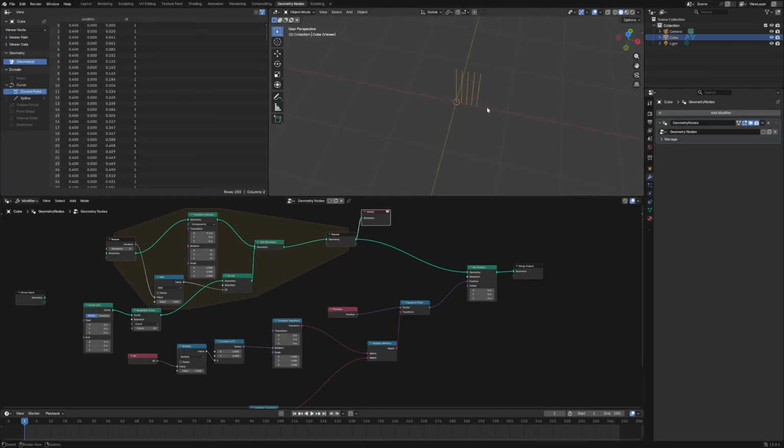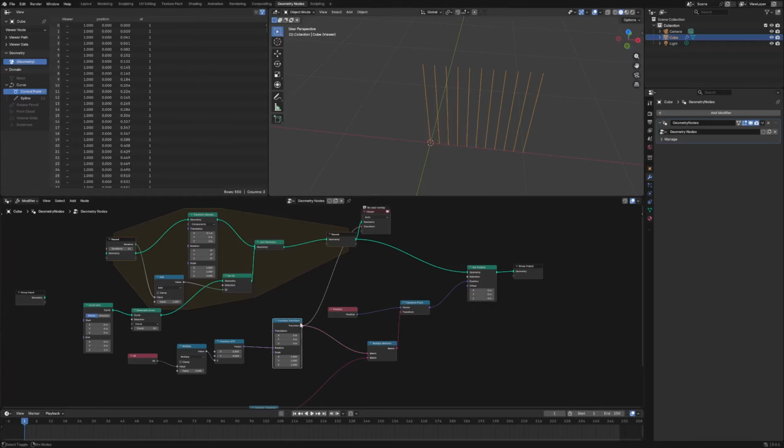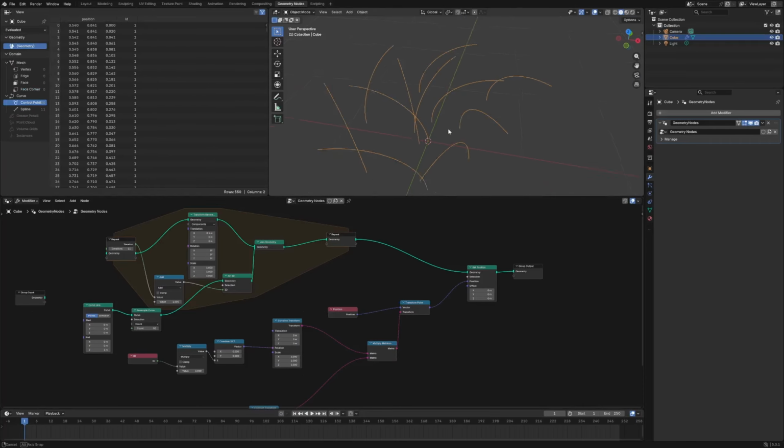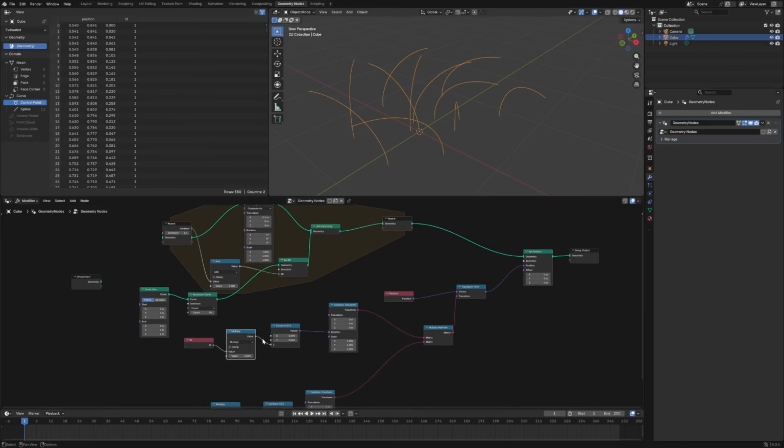So why is that happening? Basically, we're making a new spline here each time we're going off, right? We increase this count, it's going a bit bigger. And then we are using this combined transform here to have it be rotated depending on how far it is on the Z off of the ID. So that is letting us drive this rotation. We pull this down to 0, we're seeing it go here, right? So we go to 1 and it's spiraling out. So this is how it's working.